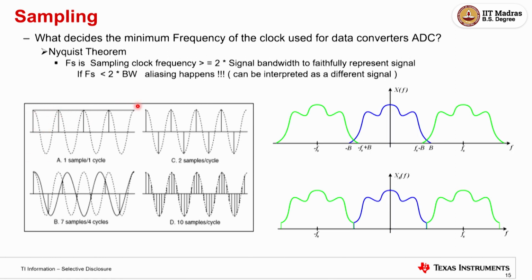That's what in the frequency domain looks like aliasing. Aliasing is basically this information not being a representation of your information. So this is the frequency spectrum. It just copies and then folds. At a concept level, that is enough to understand: it folds. This is your sampling rate and this is your bandwidth, the blue curve.